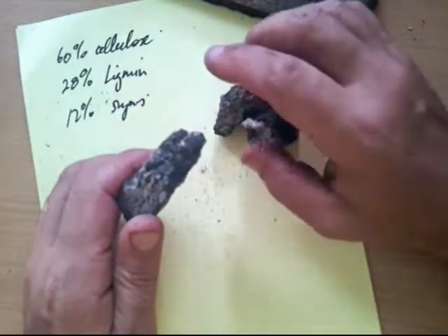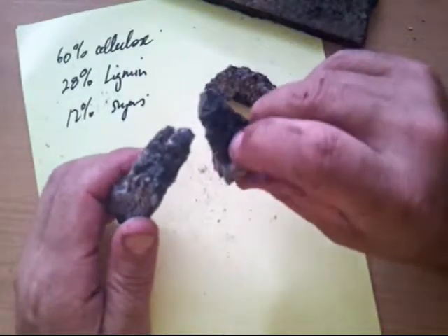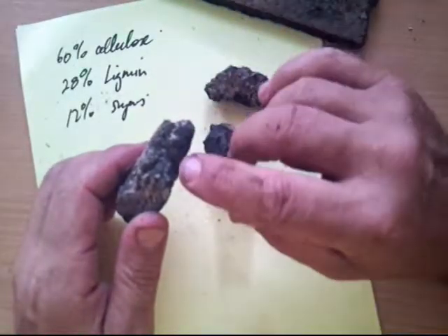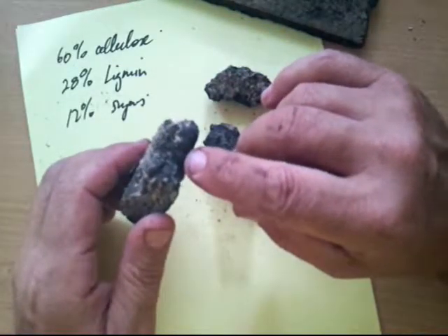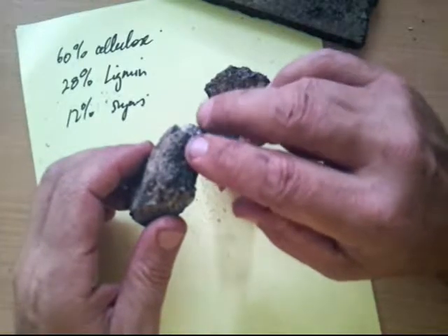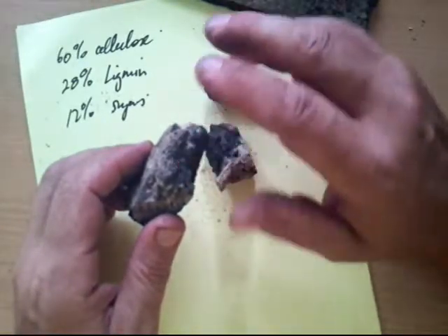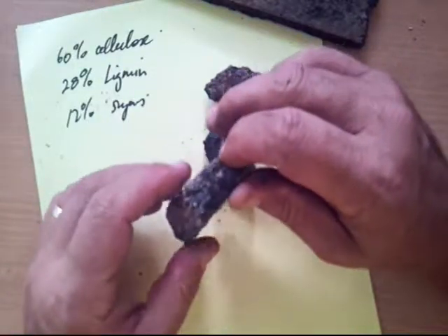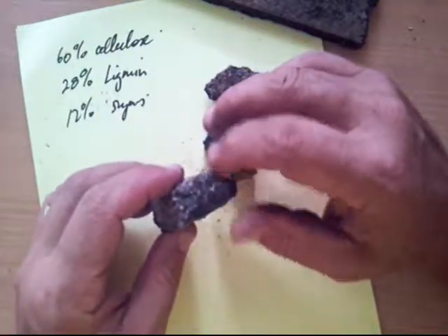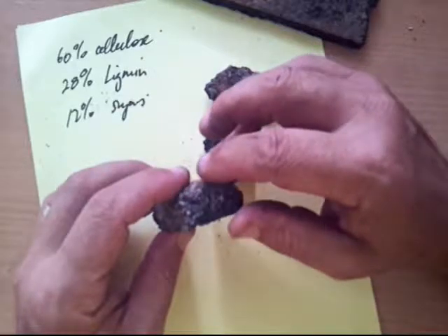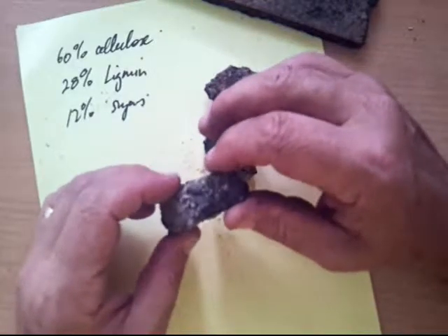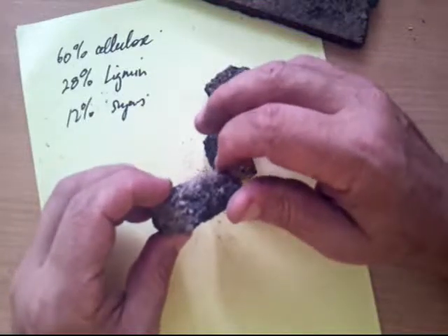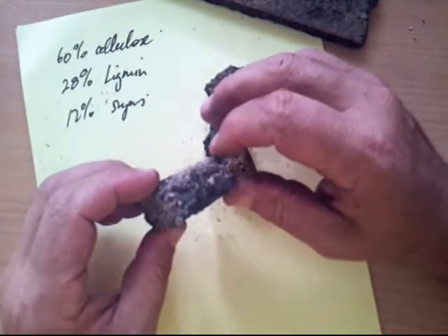Alright, so much for asphalt. Now with asphalt, it's important to notice that the aggregate that's mixed in here, just like concrete, if it's used on a road base, which is often the case, probably its biggest use, the asphalt is flexible, so it doesn't crack like concrete. It will bind together and hold harder elements like stones, etc., that will provide wear resistance, which is essential for a road. And it can easily be replaced.